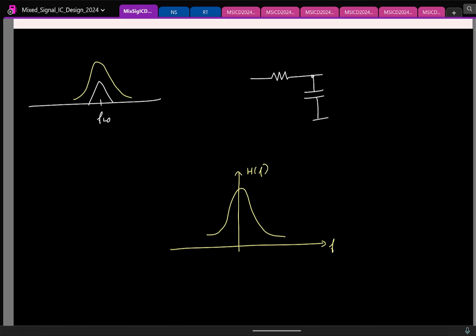That idea fine? I down convert, filter it, but that's not done. What should I do? Again, send it back to the same frequency. It's like you go to your grandma's house, have a lot of nice food, come back to your house, right? So how do you mathematically model this down conversion? You multiply with cos or sine. Let's take cos. This will down convert. Now you do low pass filtering, and then you up convert. Again do the same thing.